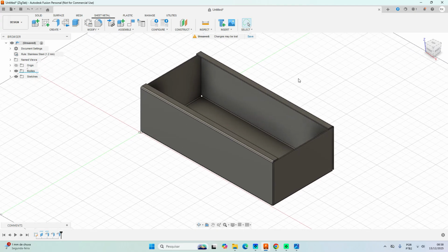Okay, so well, how do I do the holes? Okay, you have to go back in the sketches and do the basic drawing of the features of this chassis. Okay, so you click here in sketches. You will have a list of sketches you are using. For now we only have one. I will click here in this little eye to show it. You can see that we have our primitive drawing, so I cannot be confused in the future.